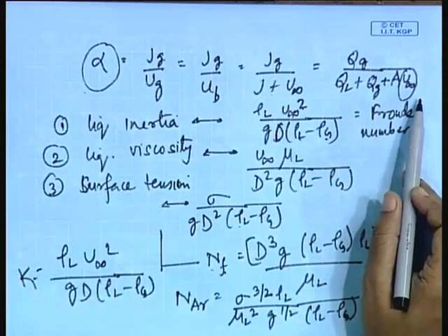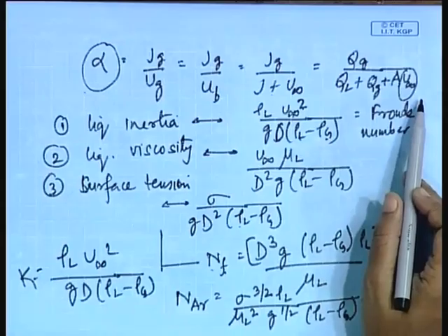What are the forces which are important here? Definitely the buoyant force is important, gas rises due to the buoyant force. Apart from that, liquid inertia is important, liquid density is important, liquid viscosity is important, surface tension is important, but gas density and gas viscosity we can neglect. Okay. Now, if these forces are important, then naturally the buoyant force will be interacting with these forces and enable the bubble to rise, isn't it?